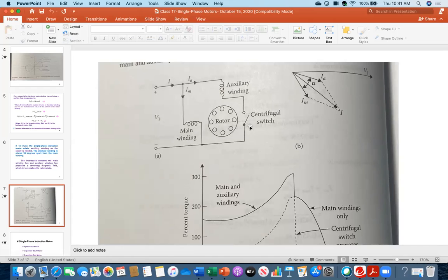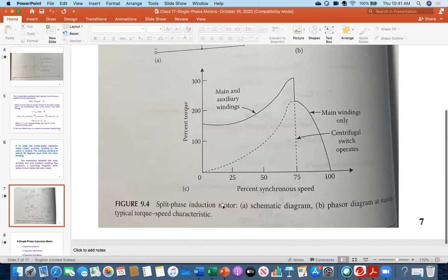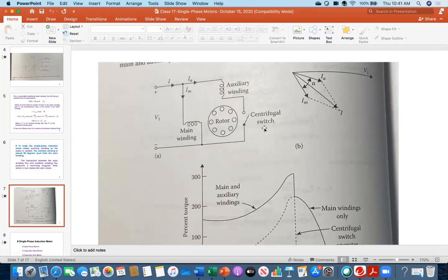And then in some cases, you don't have a centrifugal switch. There is a capacitor and that is permanently closed. So it depends on the application. This means that this split phase induction motor configuration is used for some other application, not for the ceiling fan that I am talking about. When there is a capacitor, for ceiling fan for example, the switch is always closed. For other applications, you can even see there are two capacitors connected in parallel, one with the switch. That is for a different application. Therefore, depending on the application, there are different configurations.